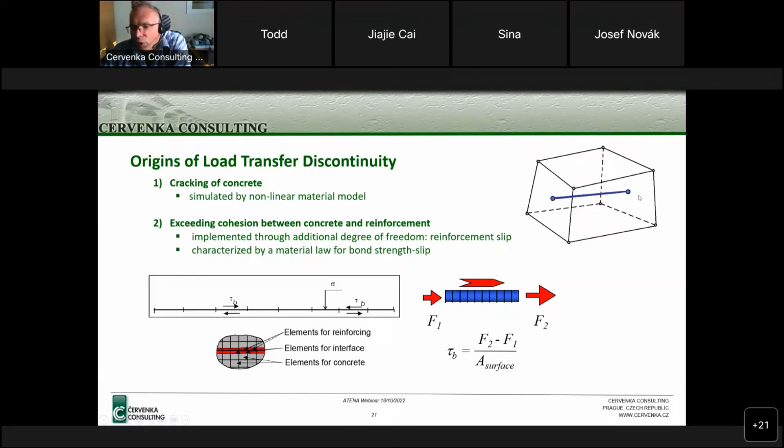And then we put some displacement constraints so that the displacements of these reinforcement nodes are compatible with the surrounding displacements of the 3D element. This is basically a simple constraint equation saying that the displacement of this node is a linear combination of these surrounding displacements. But if you think about what this means, this assumption means basically a perfect connection.